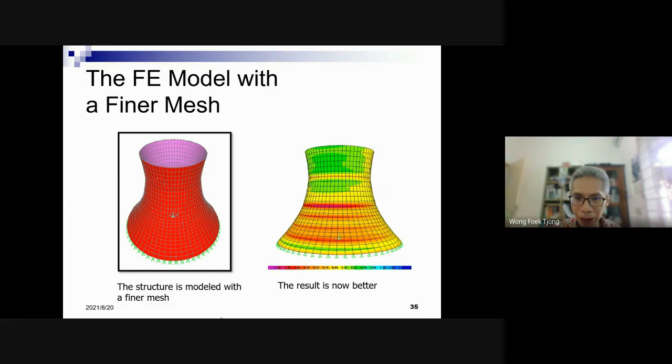What I show here is the in-plane force in the vertical direction. The meaning is that the distribution of the membrane force here is quite high. What is the value? Not so clear, maybe minus 1 point something. In what unit? You have to see the unit, maybe kilonewton per meter. When we use software, we should be very, very careful with the unit.